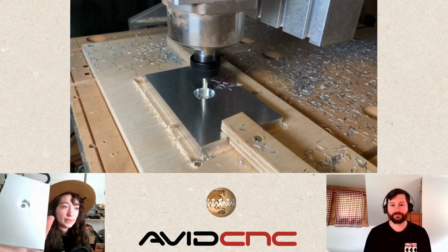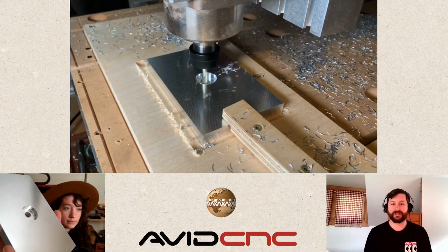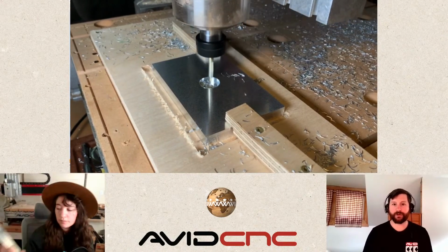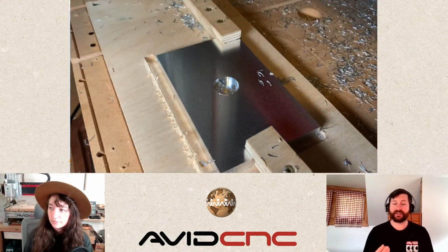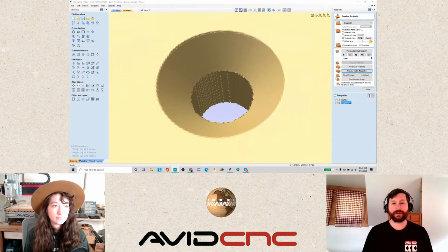Here you can see, I'll hold this up a little bit for you. We're going all the way down, and that counterbore area is actually really allowing those chips to escape. This is a great technique, even if you don't need the counterbore for a bolt. If you're going to be bolting from the other side, you can just increase that counterbore to a little bit larger than your tool, and you're going to increase your ability for chip evacuation. Whether it's compressed air, lubrication, or really good CAM techniques, when machining these types of high-density materials, chip load and chip evacuation should be exactly what is on the front of your mind when you're in the CAM space of your CAD/CAM workflow.